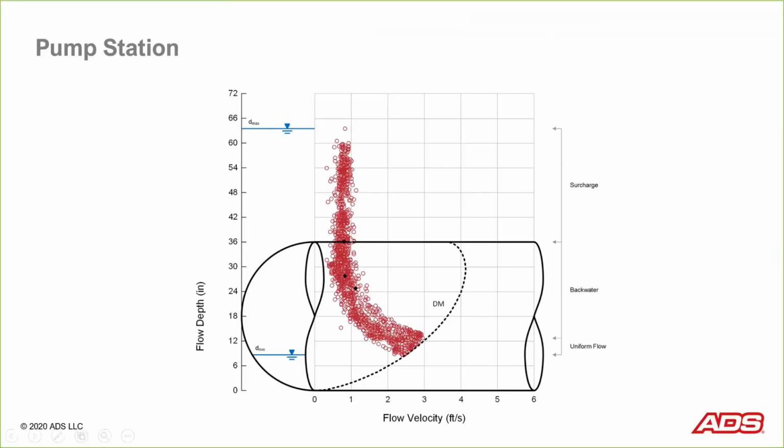You can see they do allow this line to surcharge. This data was collected during typical dry weather flows, so there's not any rain events shown here. But this is a 5-pump station, and we actually took the capacity of those lead pumps running in typical dry day fashion, and you can see they run from anywhere from 2.5 to 4.2 million gallons per day.